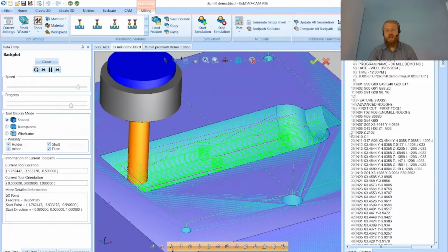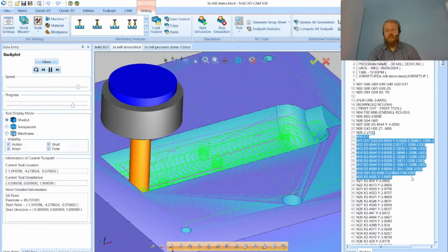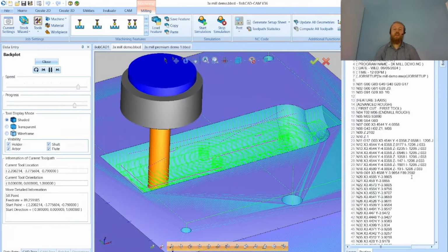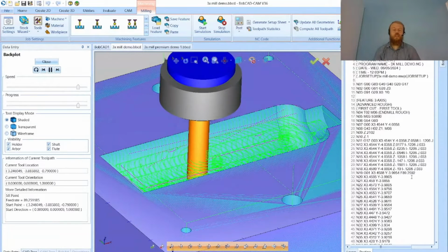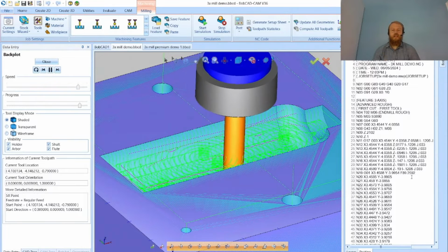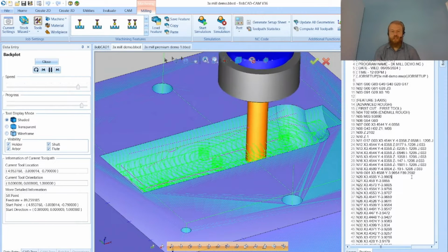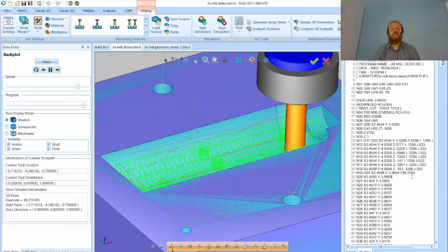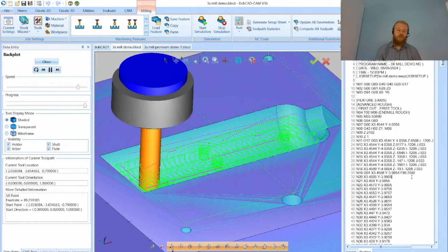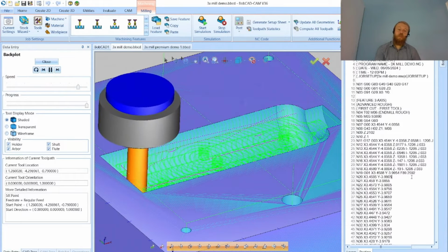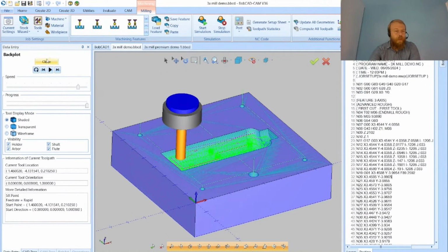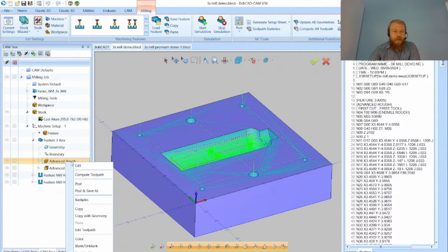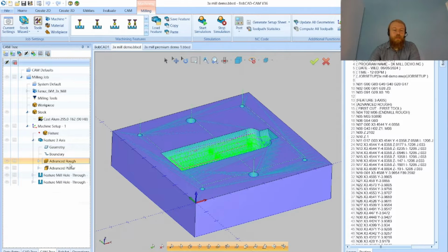In the NC Editor, it will actually read the G-code here that it's brought into NC Editor, and if there's any incorrect G-code, maybe, and I'll even show you if I add a Z plunge down into the stock accidentally, it'll show you that in the backplot of NC Editor, where it wouldn't show you that here in BobCAD. So that is our backplot in BobCAD. Our simulation in BobCAD is up at the top, Start Simulation.